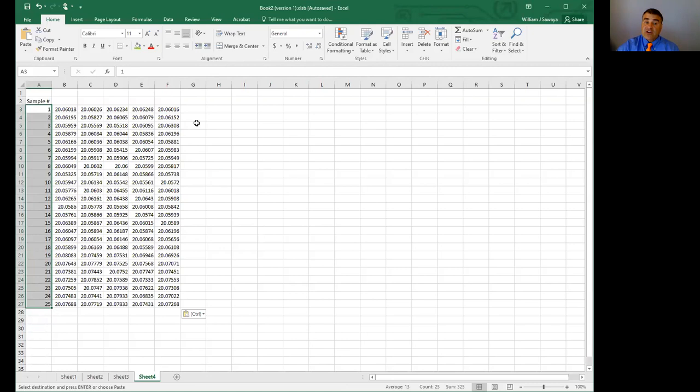Now, to make a control chart, a variables chart, we actually make two different charts. We make an Xbar chart and we make an R chart. The Xbar chart charts the mean of the process, and the R charts the range of the process. And remember, what we're mostly interested in here is whether the process is behaving in control, meaning there are no special or assignable causes affecting the process, causing it to be off.